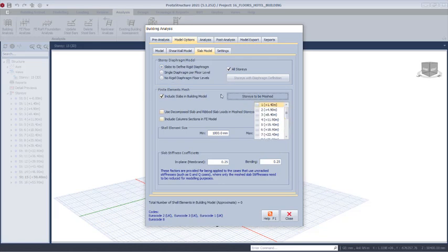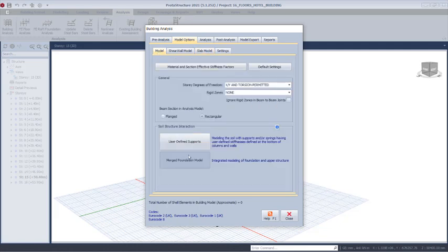You can enable that and then include the column sections at FA and all of that before you carry out the analysis. But this option is not that necessary. It's just that if you want that to be done using the finite element analysis options. The first option I've shown you, which is this one, is very important, so you have to take note of that. So we make progress. I want to be closing this right away.